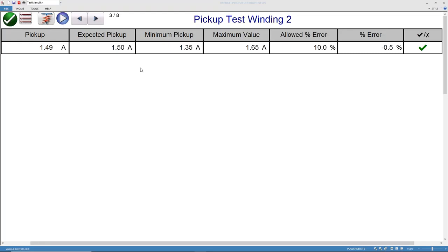This is basically how we're running these tests. You ramp up to a certain specific test value, and then you ramp back down, and that's it. You have to remember the second part of it is that there's nothing on the first winding, so we're hitting that minimum pickup mark, which is where we're actually hitting in our slope characteristic slide that I was showing earlier.